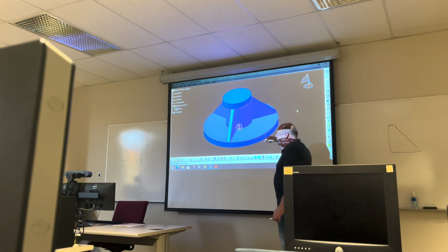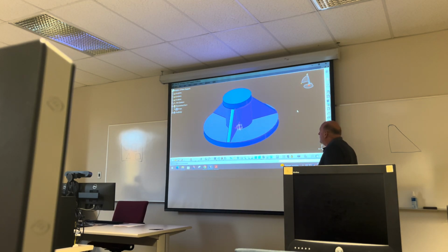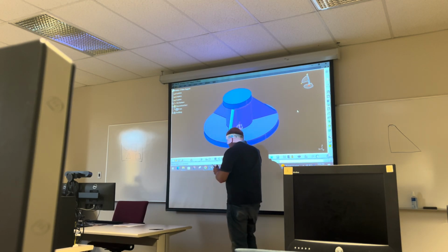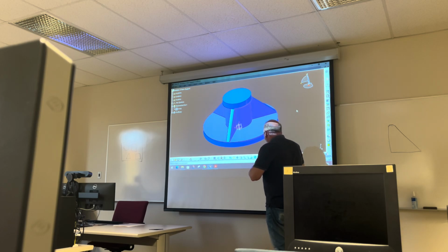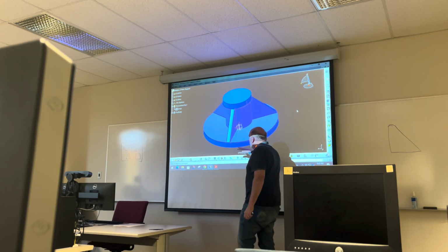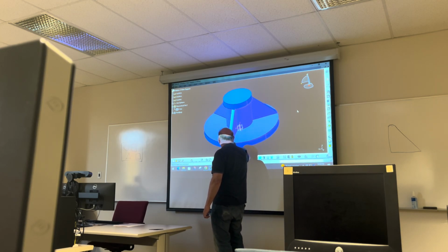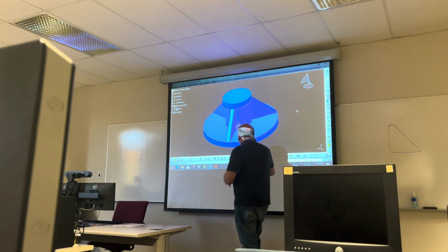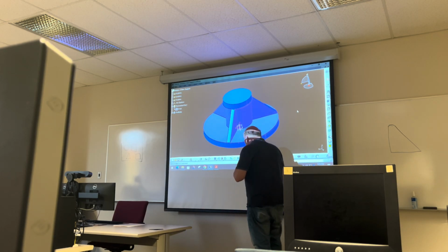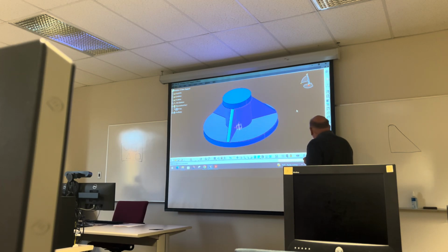When you do this as a revolve, everything's continuous, and this shape comes around you. And actually, if you ever look at a part like this, I've seen some parts that were cast that had ribs on them like this, and you can see where somebody had used that methodology of doing something that was straight. So in the casting tool, they would have had something straight, because you can see where it overhangs the edge, and somebody came back in and ground it off.